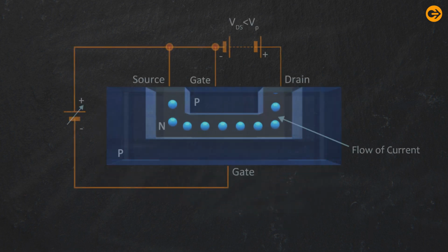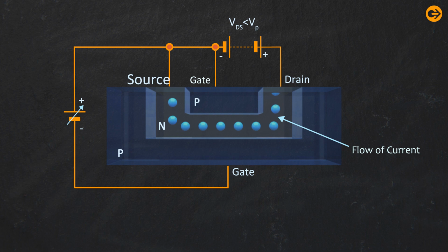Like any other transistor, it is a three-terminal device with terminals called source, gate and drain, which uses an electric field to control the flow of current through the device. The device has a high input impedance, which is useful in many electronic circuit applications.